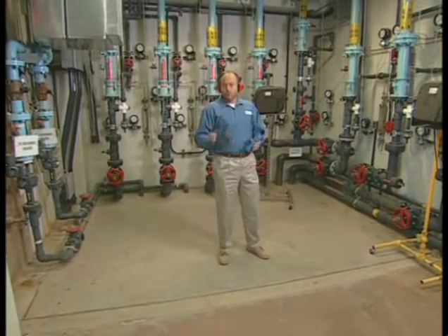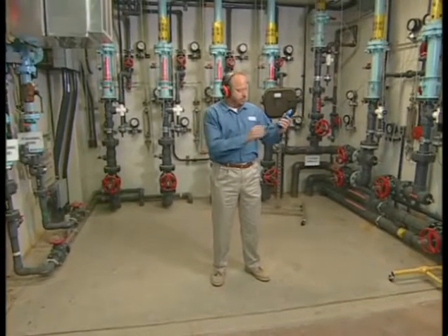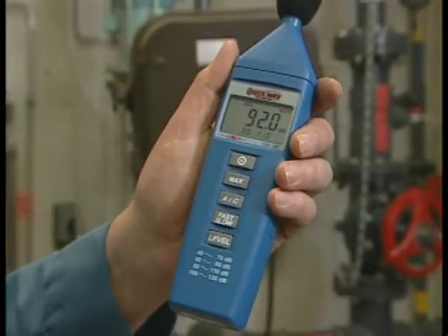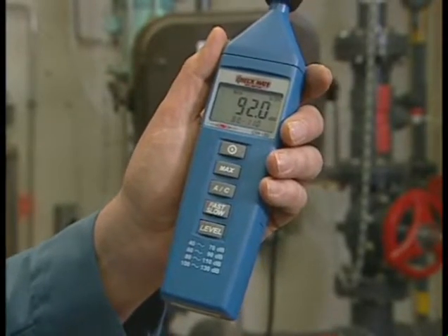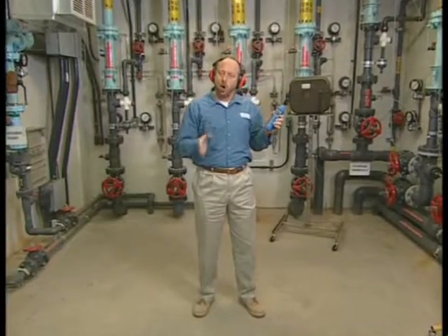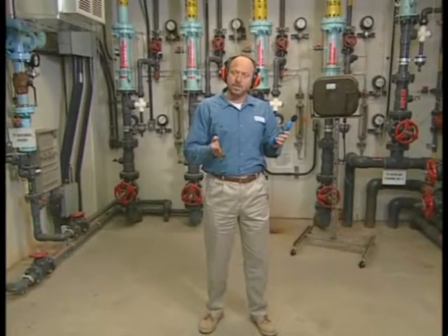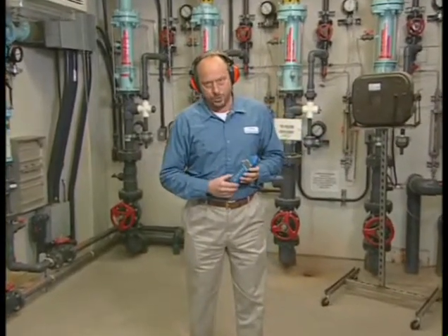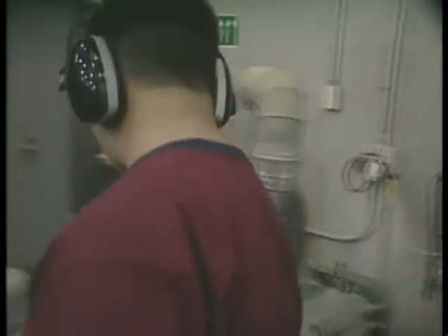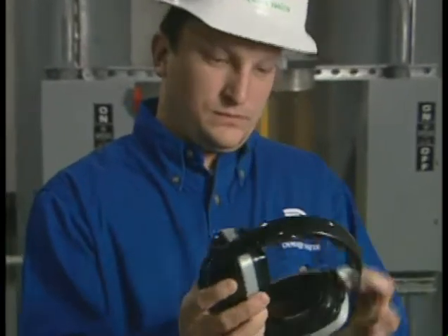The decibel level at a utility will vary according to the type of equipment used in it. By using a sound level meter, we can determine that the decibel level in this room is 92 dBs. And that's an important number to know because OSHA has identified permissible noise exposure limits for workers without hearing protection, or just how long you can subject your ears to a certain decibel level before there is permanent ear damage. It's time to talk about the specifics of personal protective equipment.